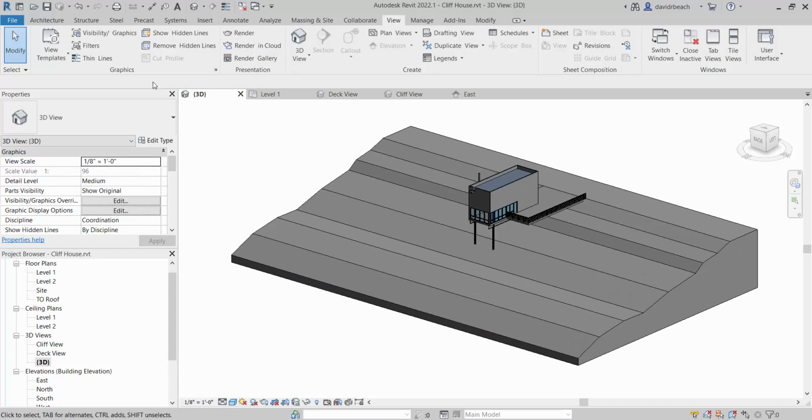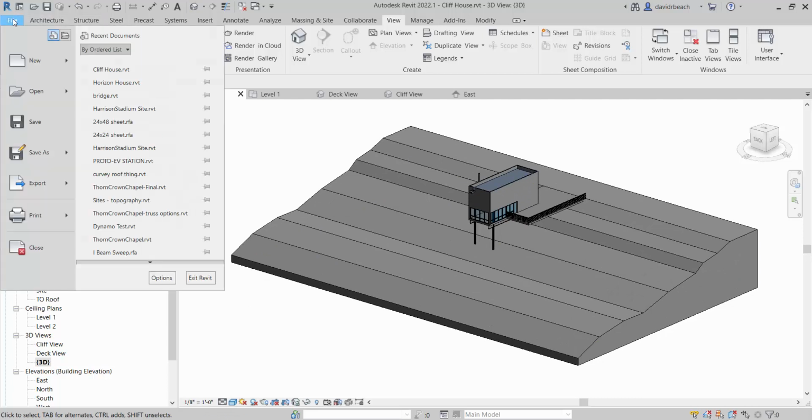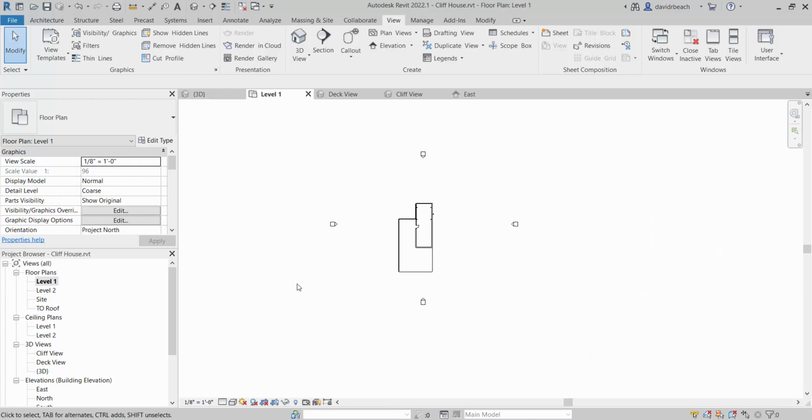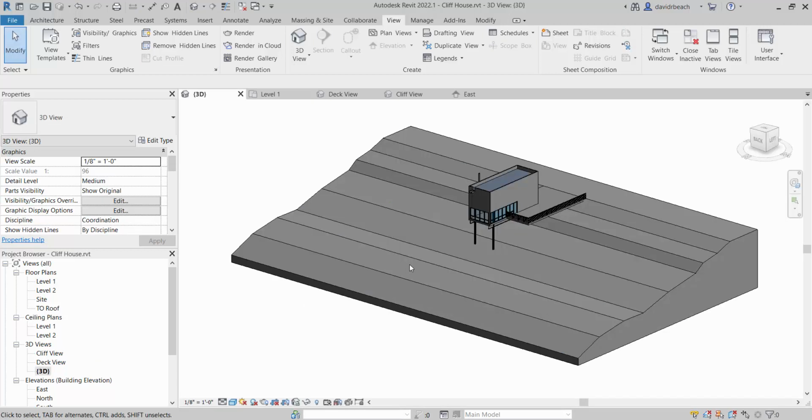But I am going to go from right here, from the three-dimensional axonometric view. And part of what I'm saying with that, if I were to export, and I haven't tried this in a long time, I'm not going to try it today, but if I export from a level 1 view, an FBX file, it probably isn't going to send all the data. I need to be in my 3D axonometric view, which can also be really handy, because I can crop things with my three-dimensional view, and it's only going to export what's showing. I can hide things in this view, all that kind of stuff.